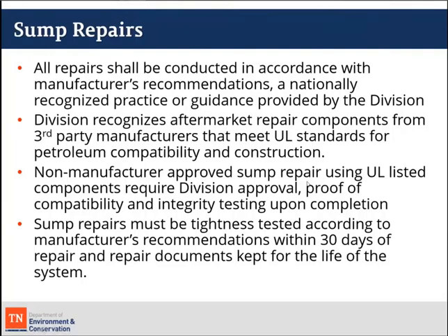Obviously, I think most people will probably perform that test within a couple days. Maybe you might have to wait for some repaired components to cure or harden, but it's important that you do go back within 30 days to test that sump to ensure that it is tight. And these repair documents have to be kept for the life of the system. So it's important that you pass on a copy to the tank owner.